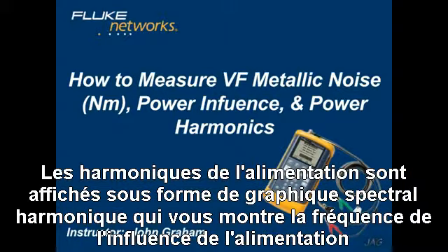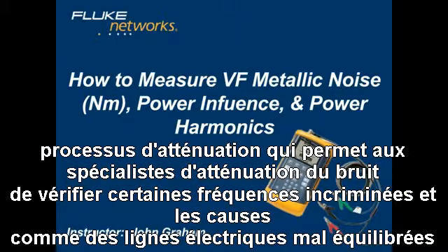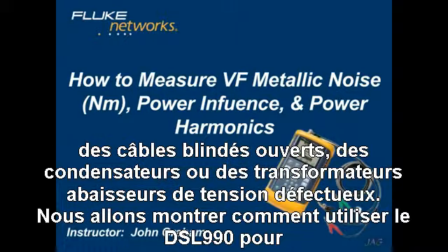Power harmonics are measured and displayed on a power harmonics spectral graph, which graphically shows you the frequency content of power influence. This graph allows you to actually see the offending frequencies that have elevated the power influence level. Identification of the offending frequencies is a key part of the noise mitigation process, as it enables noise mitigation specialists to relate certain offending frequencies to the most likely cause. Things like poorly balanced power lines, open cable shields, defective capacitor banks, or defective step-down transformers.